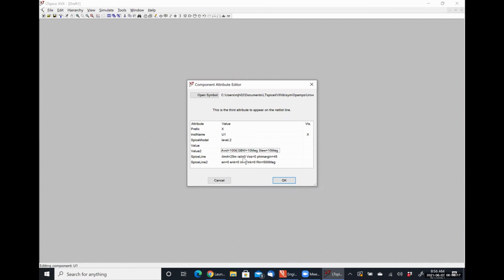So if you had a rail voltage of, say, 1 volt, that means that if your power supply voltage VCC plus was 10, your output could never get larger than 9 volts or something like that. In this class, to make it not confusing, we're always going to be dealing with rail-to-rail op amps. So we say that there's a hard cutoff at VCC plus and VCC minus. And there are certain practical op amps that are designed that way, but there are others that have a little bit more limitation.